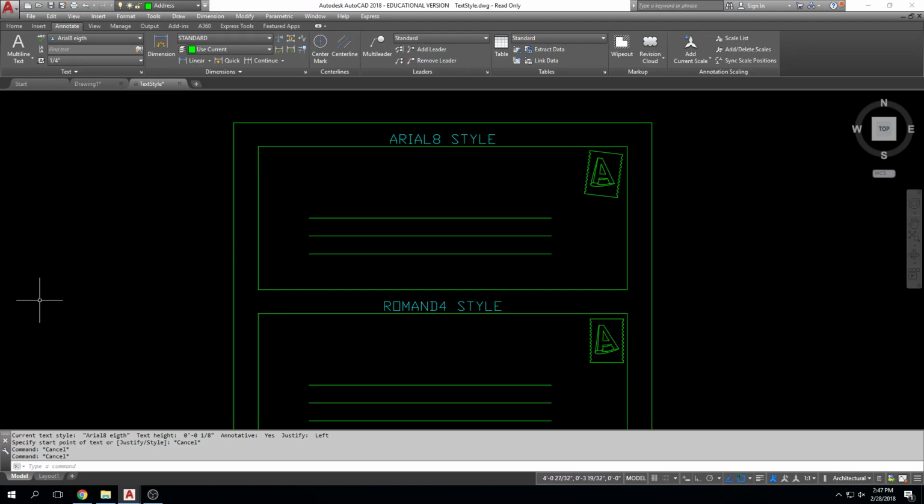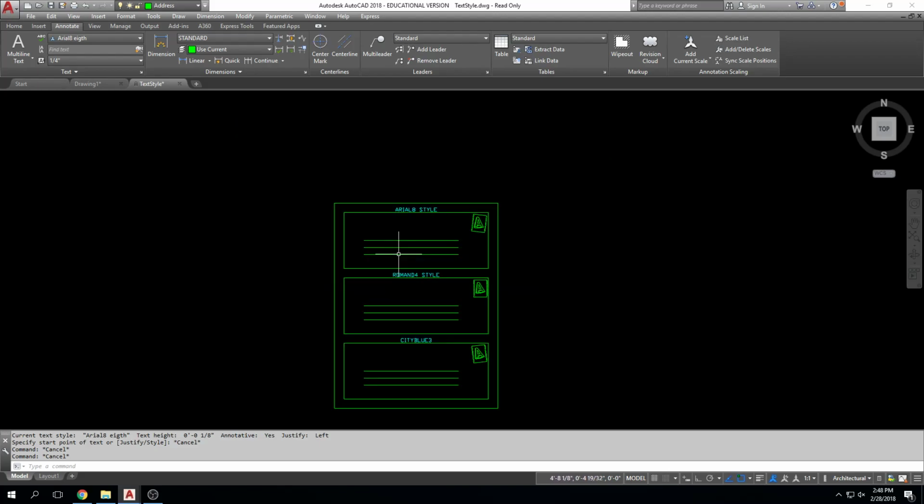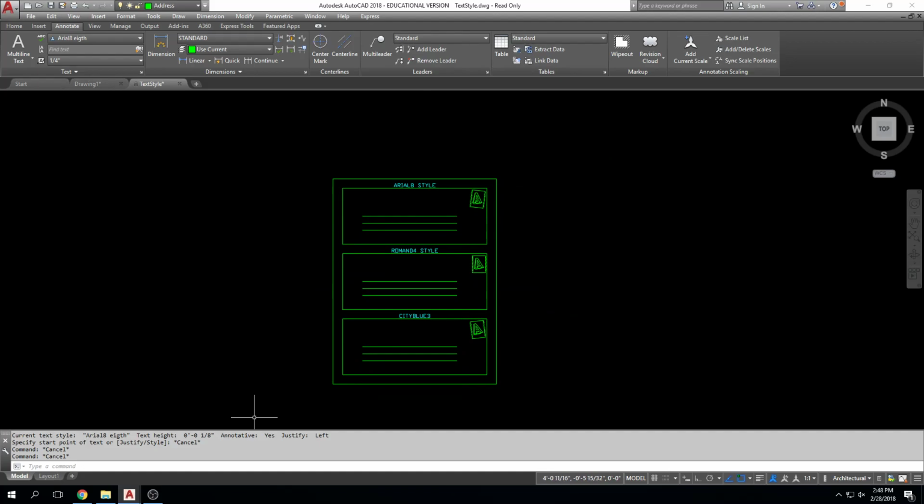model space, when I create my text, AutoCAD automatically makes it larger or smaller according to the size of text I want to achieve in paper space, right? It's kind of, we were just talking about this. This is a really complicated topic. It's really kind of hard to grasp, right? But the idea is that we have some large objects in model space here, right? We draw homes that are 400 feet by 400 feet. And if you put a piece of text that's 1/8 of an inch tall in next to this 400 foot